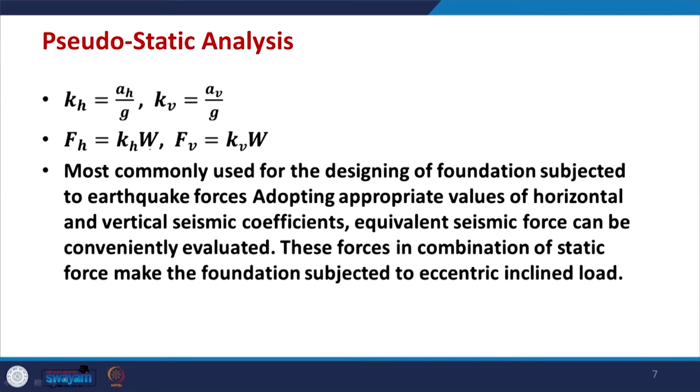So, let us first discuss pseudostatic analysis before we go for dynamic analysis. When we talk about pseudostatic analysis, you may be aware that this is the type of analysis where earthquake loads are represented by, let us say, W in this equation. W is the vertical load, and when you multiply the vertical load W by some factor, it will give you the horizontal load.